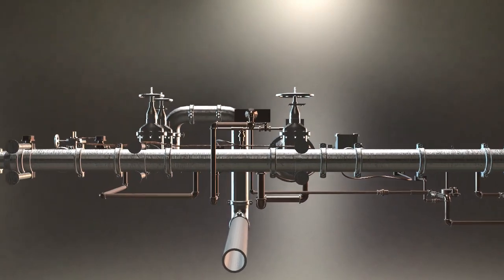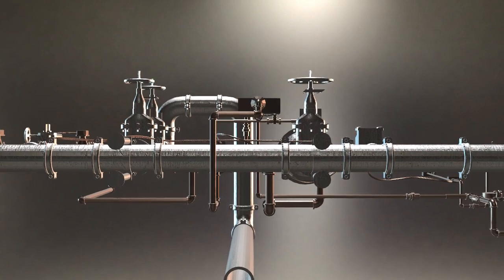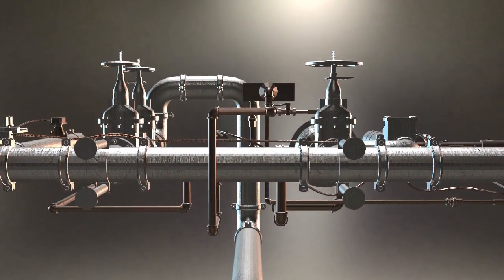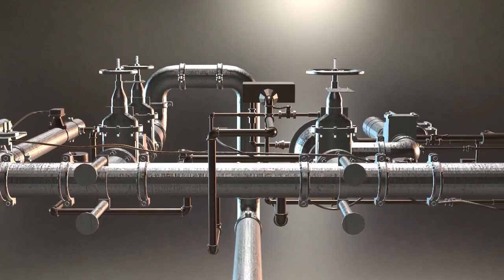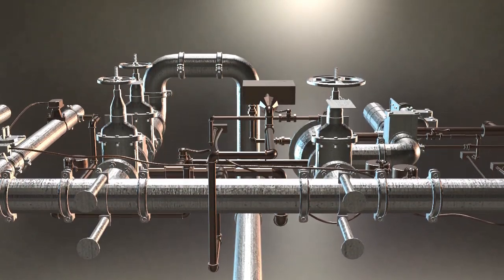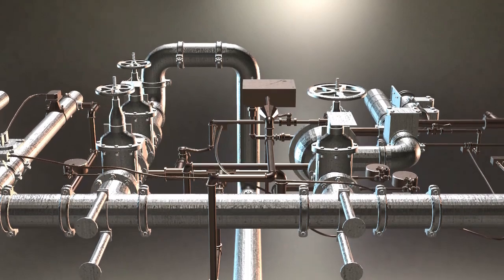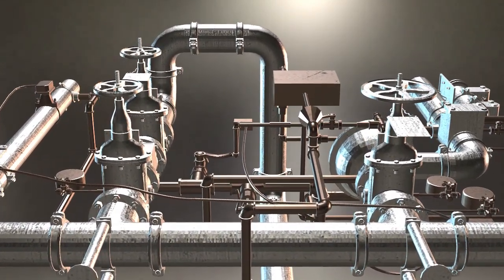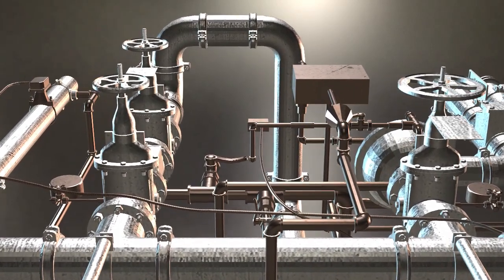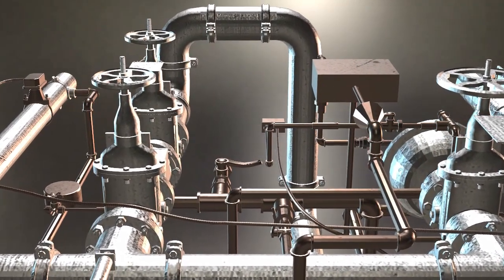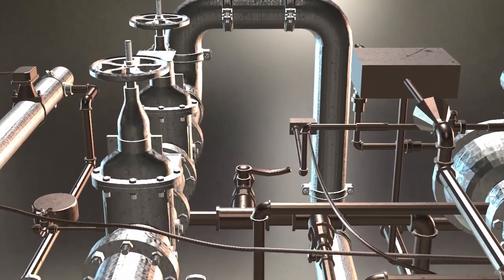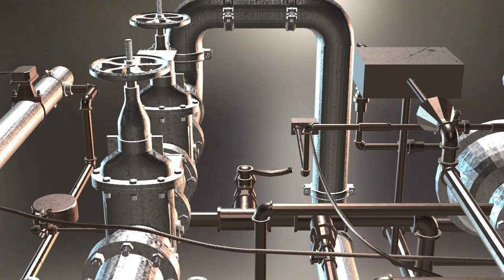In this example, we will perform a classification design of a fuel gas manifold in an outdoor location. The manifold handles natural gas, which is comprised mostly of methane and trace amounts of other compounds. The manifold incorporates on-off control valves that control the flow of natural gas. In this scenario, the most likely source of release will be a leak from a valve component.